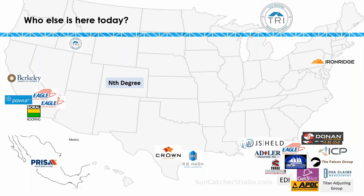I've been to a couple of Brian's jobs. He is a fantastic contractor, and one of the jobs was a concrete roof deck, brand new construction, a single family but very large home down in Hurricane Alley in Baytown, Texas, where the underlayment was applied using a primer and then foam adhesive. So there were no mechanical fasteners on the entire roof right in Hurricane Alley. And another large project in downtown Houston, a high-rise hospital, was installed with MCA tile.